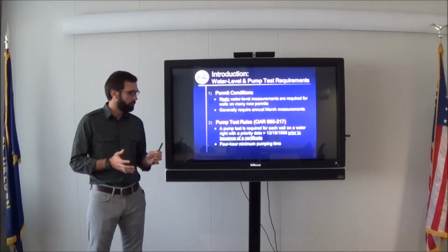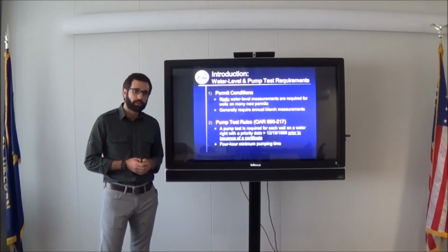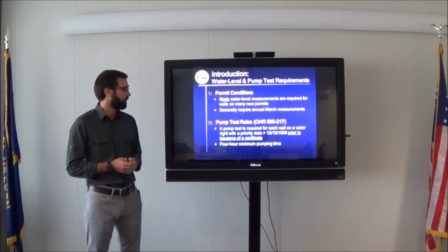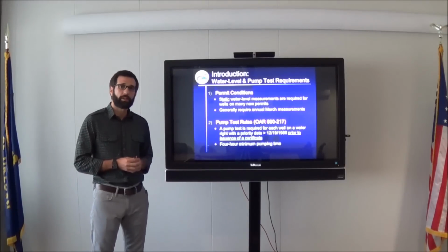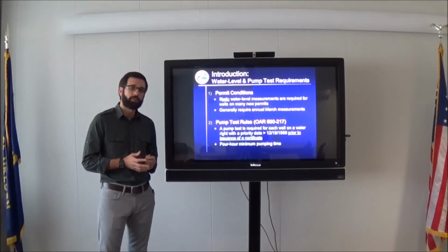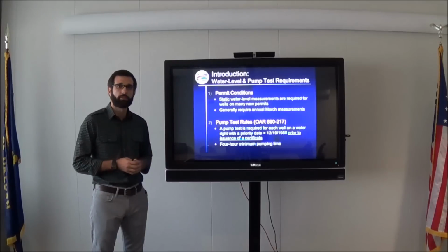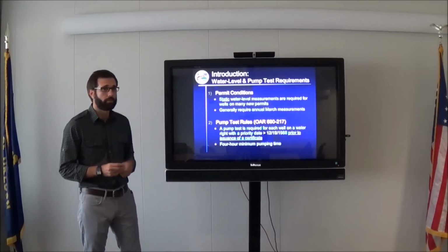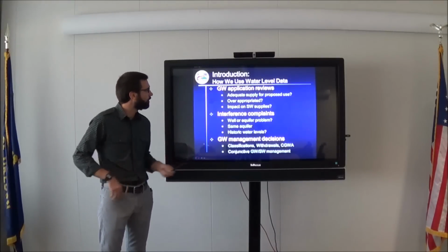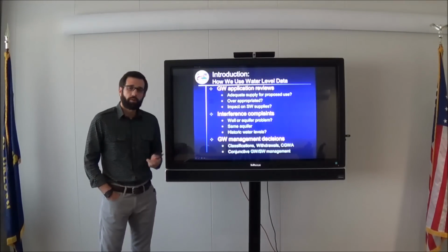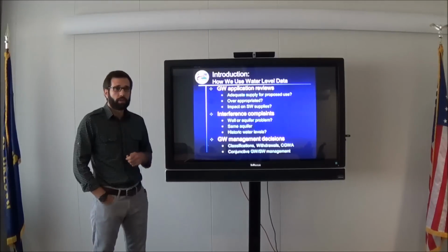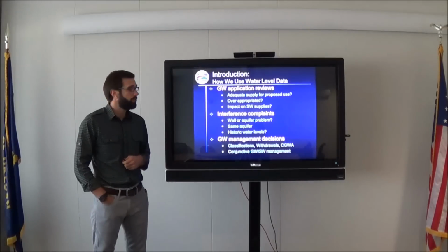And then in our pump test program, we require a pump test on any well on a water right that has a priority date that's greater than 12/19/1988 before we issue a certificate. And we require a 4-hour minimum pumping time on those. Now, the water level data that's collected as part of those programs is integrated into our databases here.